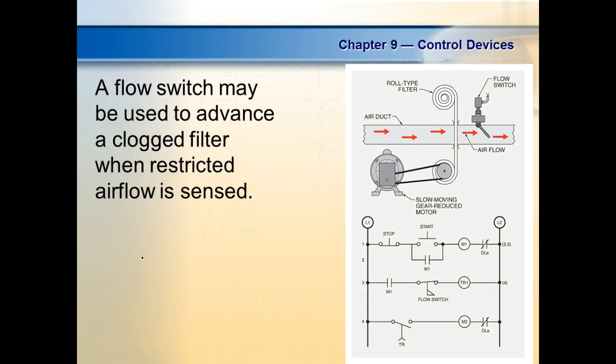An off delay timer, I got off delay. Y'all probably run an off delay timer in your car all the time. When I open my doors, my headlights come on. When I close my doors, they stay on for a while. A little while. That would be an off delay, right? Your dome lights used to go off instantly on older cars, but now when you open your doors, they'll come on and when you close them, they do what? They stay on a little while, right? So those are examples of off delay timers.